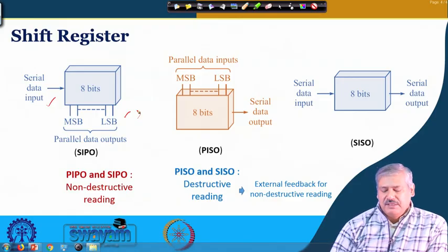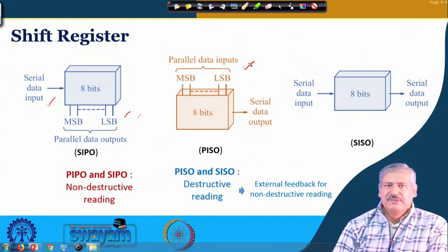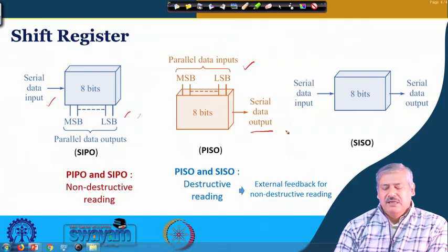The other type is where data is sent to the register parallelly. In one clock cycle all the data is getting loaded, unlike the previous case. And then for the reading part, the first data in the inmost flip flop is available, and then if it is 8 bits, you need another 7 cycles to push data out of the flip flop.